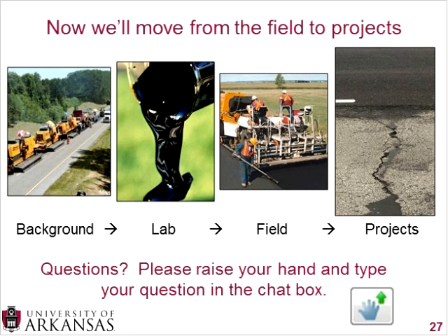However, just based on visual observation, and we'll see a couple of projects here, the HIR that was recently put down, I think that you can have just as good a ride quality off HIR jobs as you do a traditional hot mix job or warm mix job, just as long as you go through the mix design properly and then the construction properly.